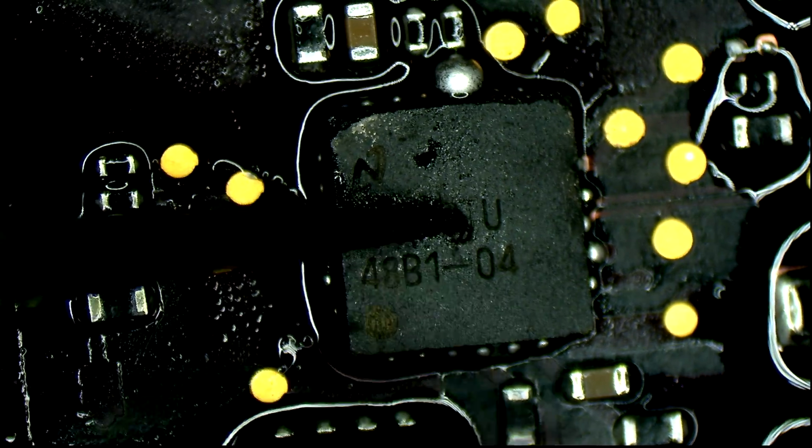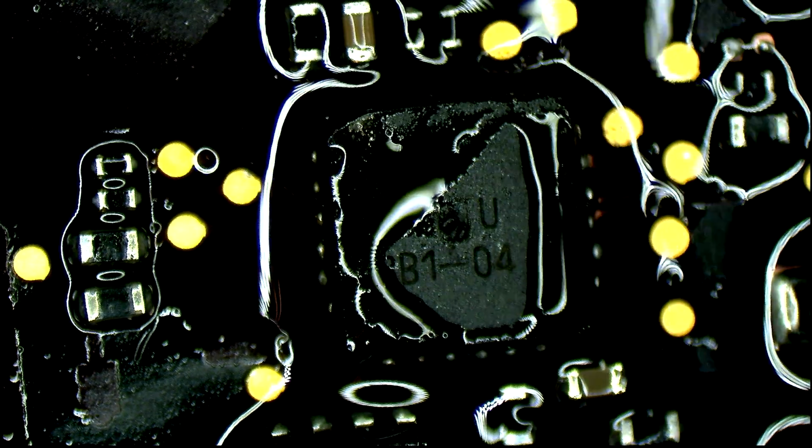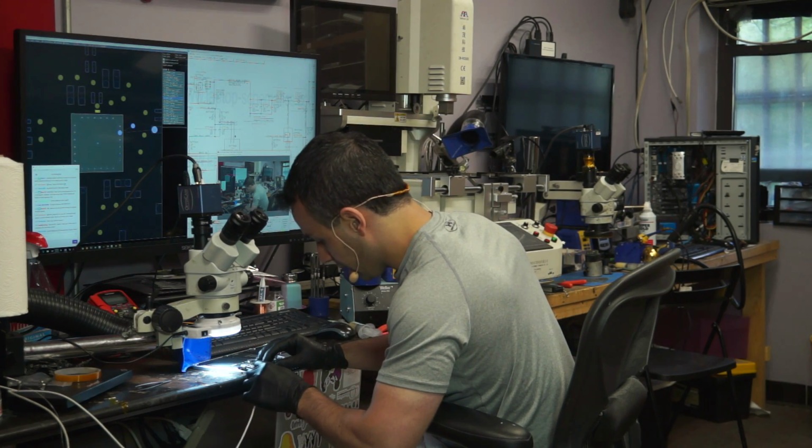See, the fact that solder is popping out means that it wasn't perfectly flat, which it's not going to be unless I get a perfect amount of solder on the center pads, which I never do. So now we're just going to get rid of the excess on the sides, and we'll be good. This is where the fine tip comes in handy. And let's see what we get.